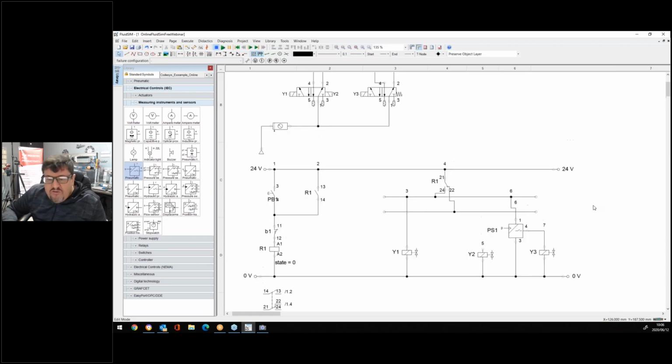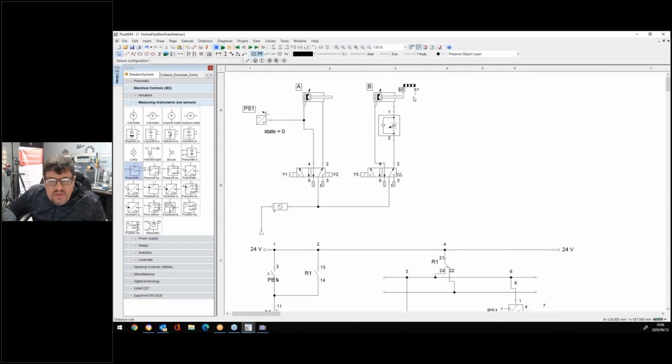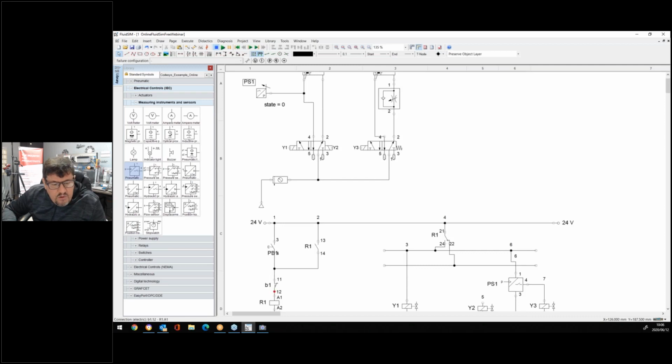Right, now as it goes forward, it reaches B1. All right, now check what happened. The moment when it reaches B1, it will open within my start circuit. And as it opens in my start circuit, right in the start line, your latching part will fall out, and the relay R1 will then change contacts from the normally open back to the normally closed. Then you will power this line.